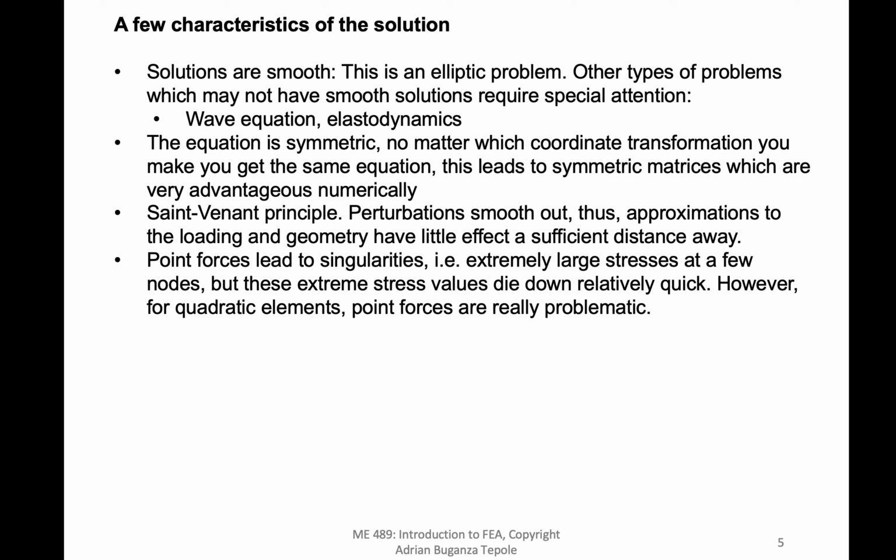Then, the same Saint-Venant principle, which is that perturbations smooth out. So you don't have to have the perfect geometry or the perfect loading. You can have some approximations to the loading or the geometry. You might not capture absolutely all the details of your geometry or the perfect loading scenario, but you'll have some error, and as you move away, that error will decay.